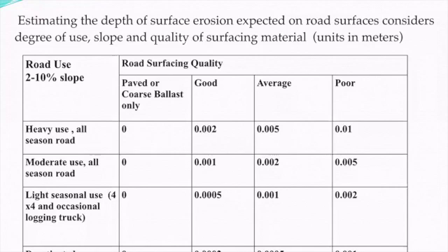It is important to determine what type of road you are on to determine the amount of sediment you expect it will generate. Remember, we are not yet discussing what sediment is getting into the stream, just what the road itself is generating. A road could be generating a lot of fine particles, but that sediment may not be connected to a stream and therefore will not play a part in its water quality degradation.